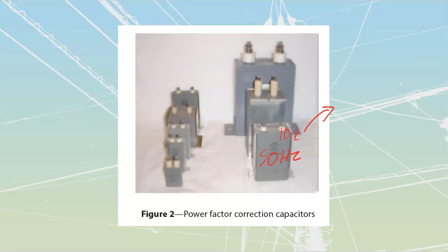Take a 60 hertz cap and work that thing, take a 50 hertz cap and work that thing onto a 60 hertz system, because you will at times run into European or Asian equipment that is designed for a 50 hertz system that is then going to be placed onto a 60 hertz, and it changes all the values inside there.